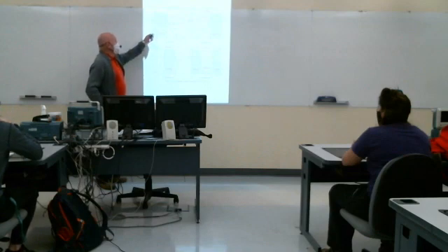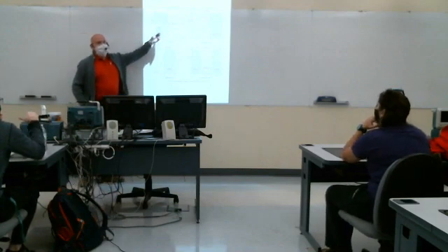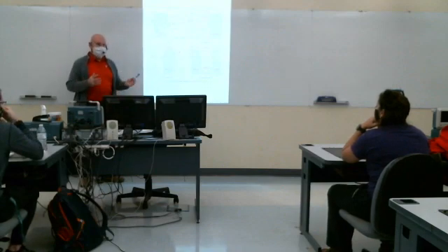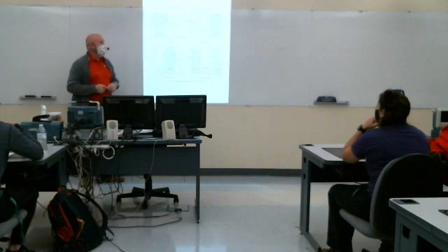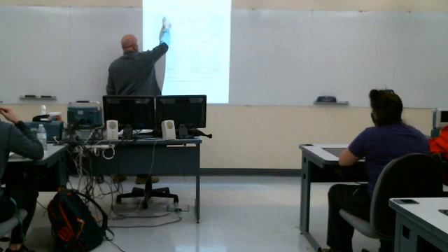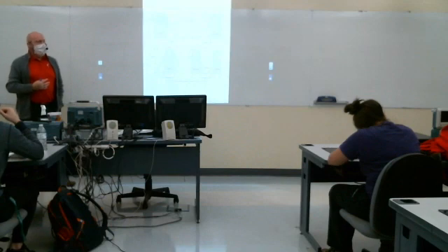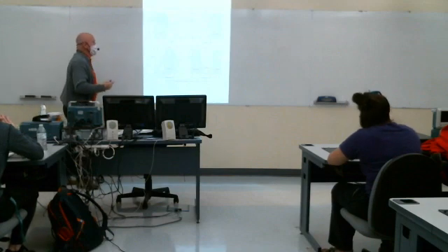The one in the upper left is called a low pass filter. It's intended to pass through low frequencies and filter out high frequencies. Of course, that's all relative. We really have to define where the corner of this thing is. Now they show here this blue line, which is the typical response of what we call a first order filter, maybe made out of a simple resistor and capacitor, or resistor and inductor. Sometimes they're sufficient. They do good enough.